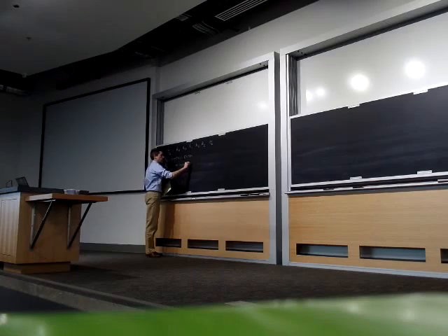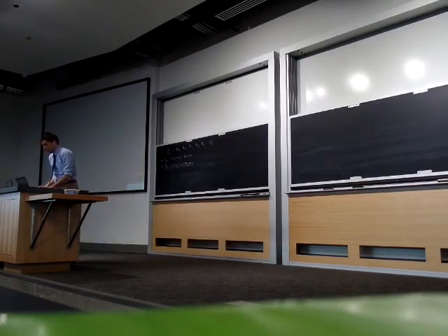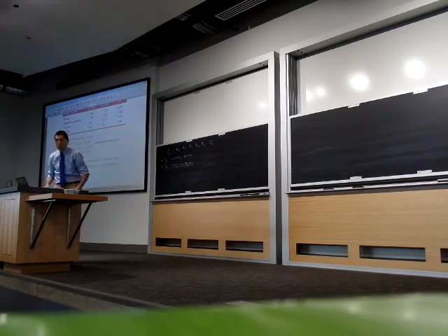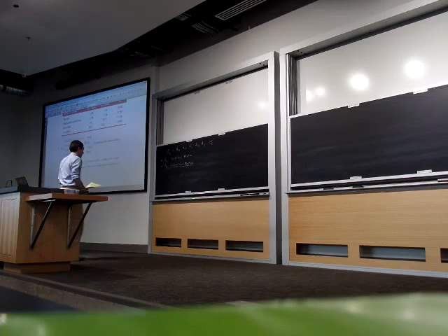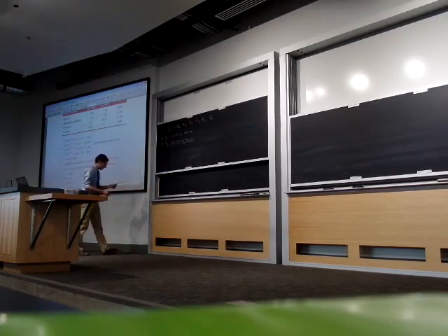And remember, physically what these parameters represent is how different is your actual mechanical element from your Moore specimen. And that needs to be reflected in these endurance limit modifying factors. So the first one was focused on how the surface quality is different. The second one is focused on how the geometry differs from the Moore specimen.